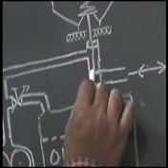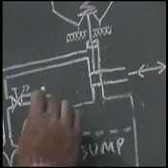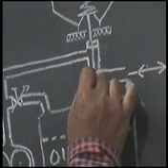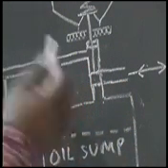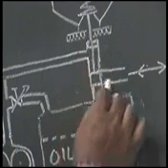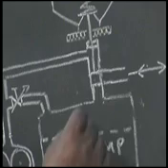So there is every possibility that the pressure of the oil will force it down at all times, and thus the oil will be flowing to the cylinder at all times. So what to do? A hydraulic balance of this rod has to be arranged.